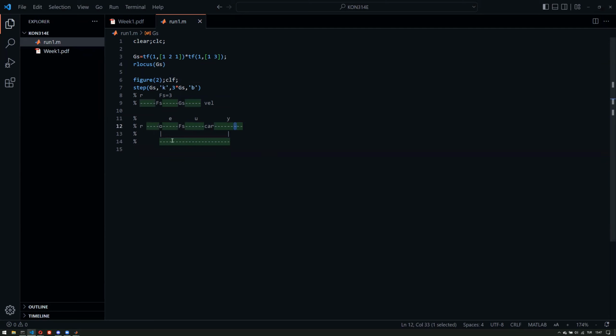This is taking a measurement from the output, looks at the input, looks at the difference of the reference input and the output, and looks if there is an error. If that's the case, then you are basing your control input, or the system input, on that. So what it really translates into is that you will change your gas pedal angle, for example. If your speed is low, you will press it a little more and increase your input. So this is the control strategy here.